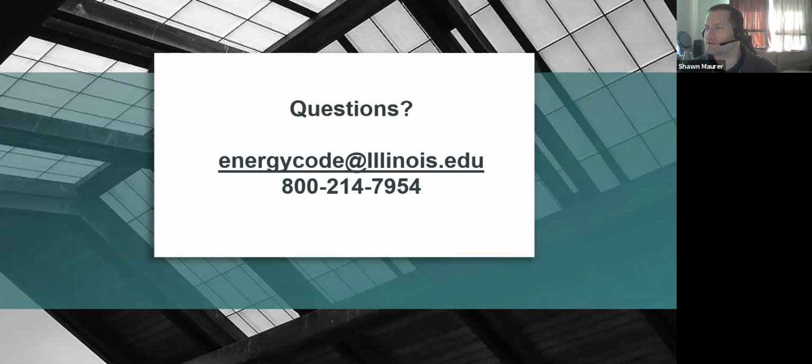We did have a question come in early on about if we could elaborate on the products available to protect exposed insulation at slab edges. Some of the different things that we have seen used, particularly at doorway thresholds, overhead doors, and access doors to buildings. We've seen the insulation trimmed down for a 2x4 or 2x6, whatever is required to cover that gap, or some other kind of non-conductive material placed on top of the insulation just to provide a little bit of structural support and protection to that insulation.